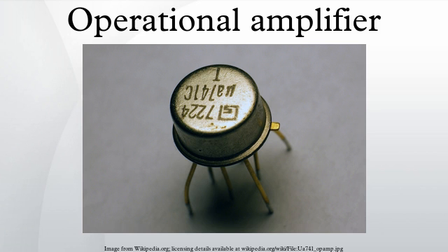Output amplifier: the output stage is a Class AB push-pull emitter follower amplifier. It provides an output drive with impedance of approximately 50 ohms, in essence, current gain. Transistor Q16 provides the quiescent current for the output transistors, and Q17 provides output current limiting. Biasing circuits provide appropriate quiescent current for each stage of the op-amp.